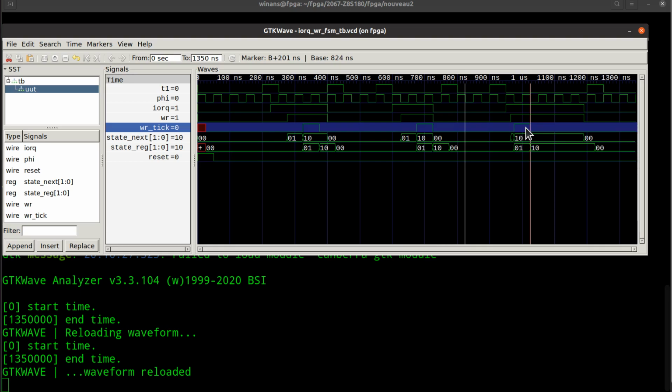Okay? Now, you might argue that this is actually better, and during an I/O cycle, it would be better to grab the data on the falling edge of T3 rather than the falling edge of TW. Yes, you can do that. If you want to do that, just advance your state counter another tick and count up to 3 instead of 2, and assert the tick signal when it equals 2 instead of when I set it equal to 1. All right, so you can move this signal around, is my point, if you want to. I left it clocking early